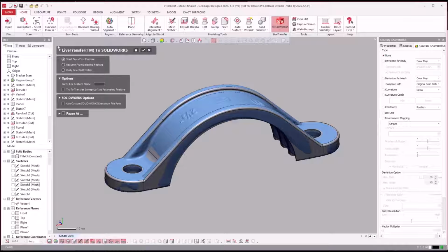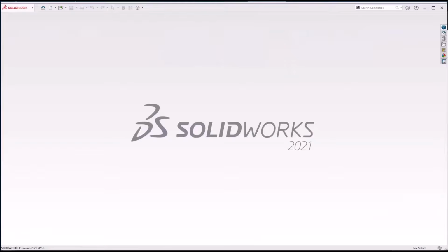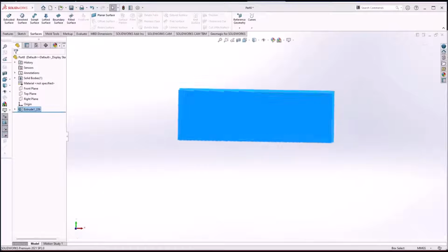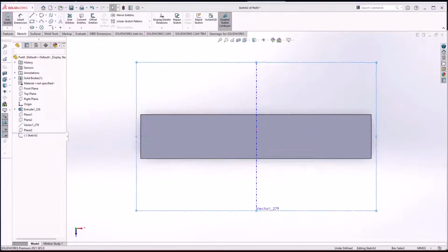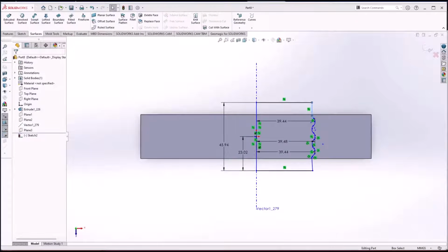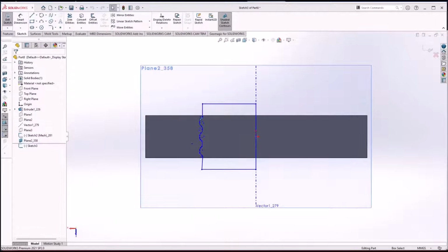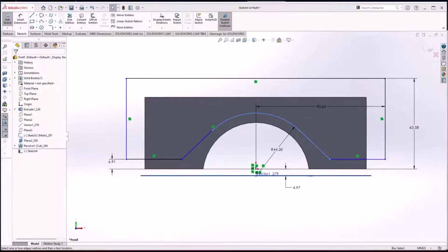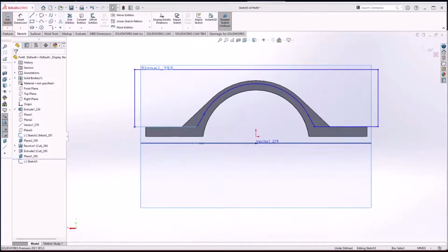Now I'm going to show SOLIDWORKS. So here is SOLIDWORKS. We'll go ahead and hit the OK send button, and you'll see it creates a new part. And I do get questions sometimes: you can send this into an existing part. So if you had some stuff modeled and you extracted some of it from scan data and you wanted to update your model, you can do that as well. So it is possible to send into a current part.